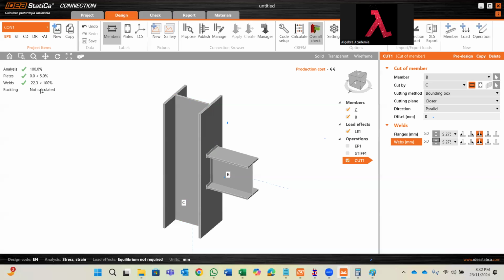Because the weld has 70 percent of the area of the weld multiplied by the weld grade. It is a huge capacity, even with a 3 mm thick weld. But due to the authority requirements, I have to go for a minimum 5 millimeter weld thickness. Is it clear, everyone?